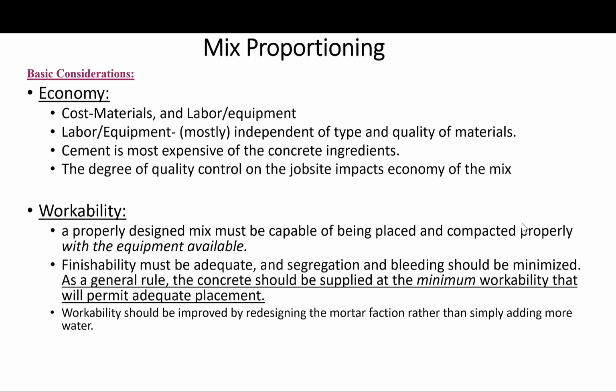So as a general rule, the concrete should be supplied at the minimum workability that will permit adequate placement. For concretes without mineral admixtures, the water requirement for workability depends mostly on the characteristics of the aggregate rather than those of the cement. Remember what we said when we talked about the fresh concrete properties and the aggregates.